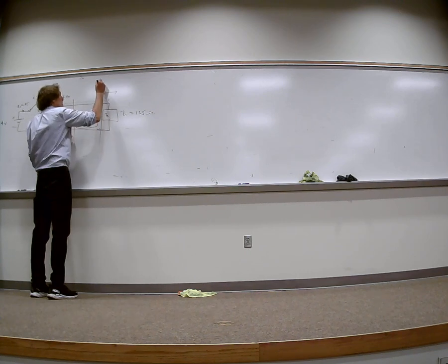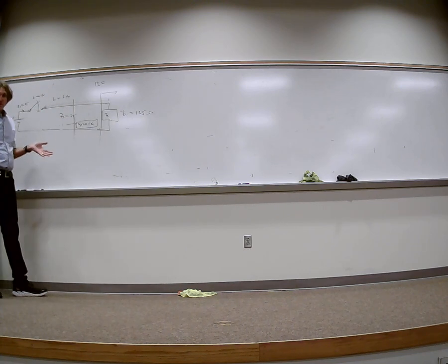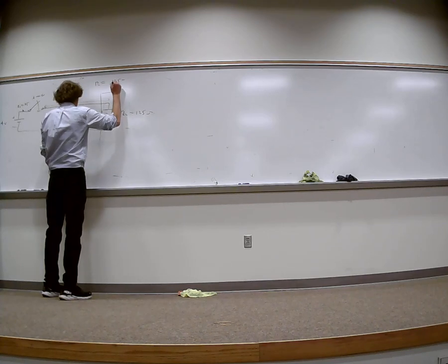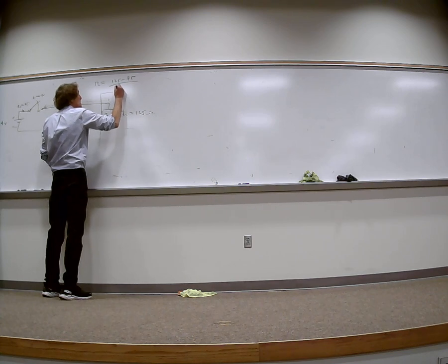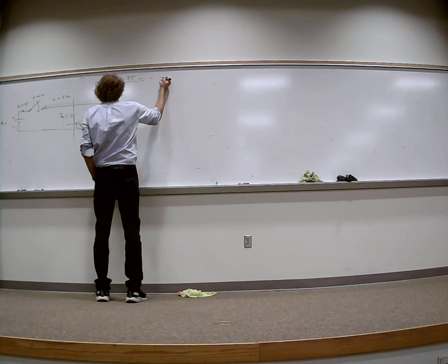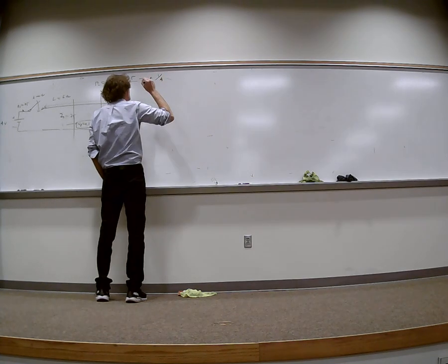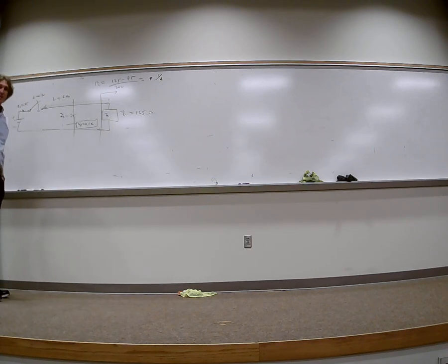First, I'm going to get the reflection coefficient of the load. It's always the impedance you're going into, 125, over the impedance you came from, over the sum of the two, which is 200. So that's going to be minus 1/4, isn't it, class? I'm sorry, positive 1/4. My bad. You all with me on this, class? Positive 1/4.